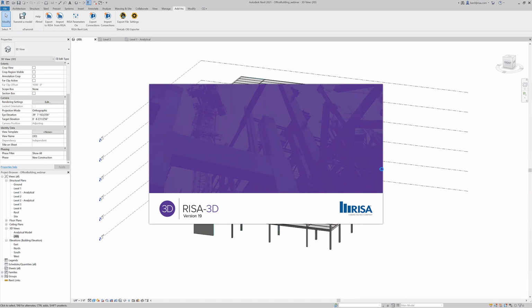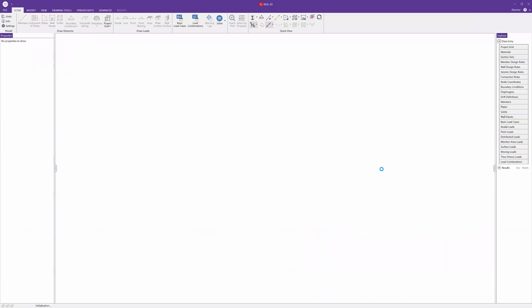Now, one of the things that we're able to do in RISA-3D is, just like we can define load combinations that are being designed for concrete or masonry or what have you, we can also define the load combinations that are going to be used in the connection design. So if you wanted to do LRFD or ASD connection design, that's fine. You can choose to do that. You could also choose to omit certain load combinations if you want to. All that's possible, so you have the control to only look at what you want to look at.